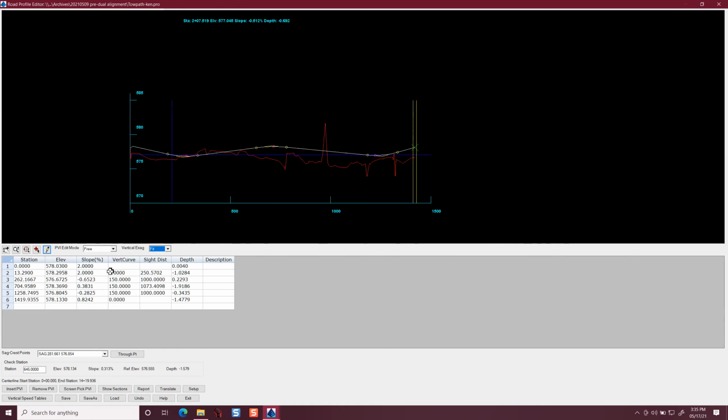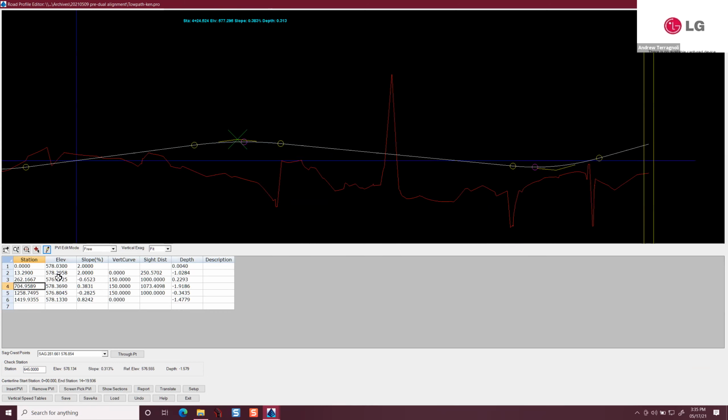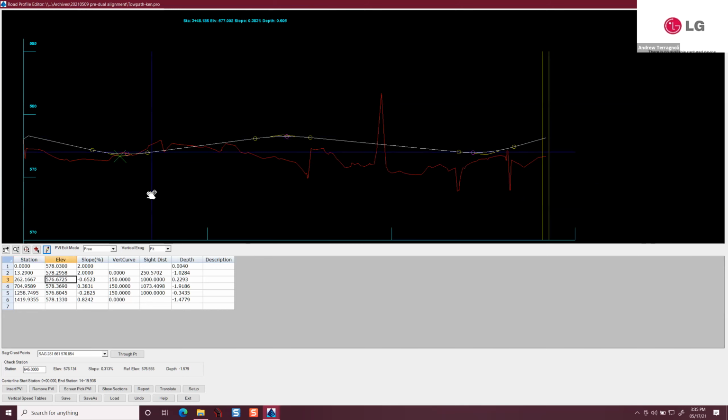So what were you saying? You say 0.5 is your minimum? Well, technically they don't want a gutter, even if it's a concrete gutter. I've never gotten a concrete gutter under 0.4. Right. If there was no concrete gutter, there's no way they would even consider anything below 0.5. Now that I have a concrete gutter and a curb, they'll reconsider that.